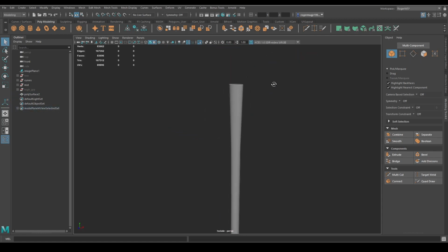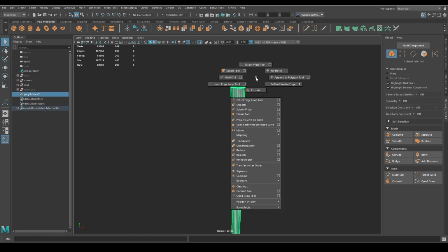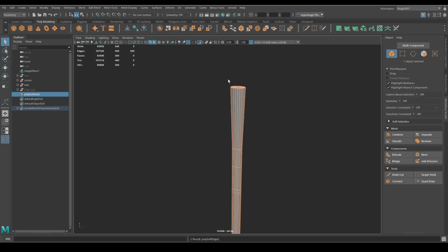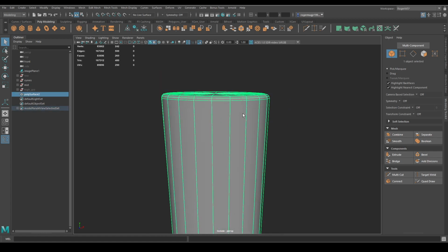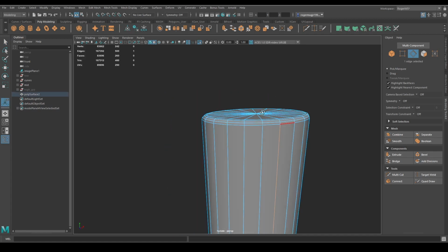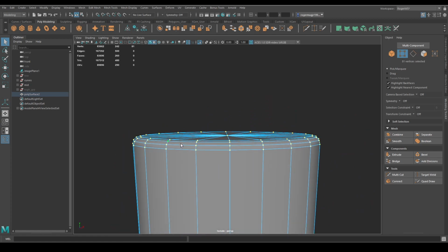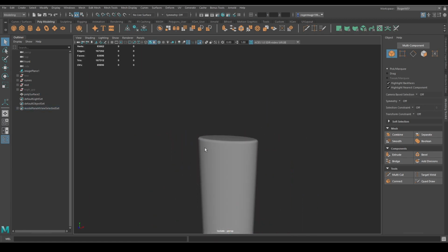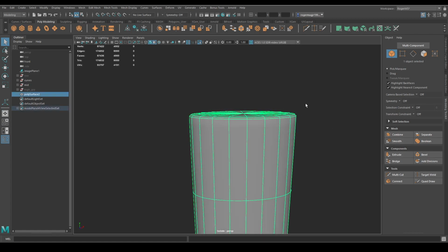Yeah, something like that. And I selected the mesh, shift right click, soften harden, soften edges, and it softens everything. And like I was mentioning before, as you can see, when I selected the bevel, I left chamfer on, so the bevel is applied to the mesh, like it makes it round instead of having just the support loops. So this way it looks nice even without clicking 3.